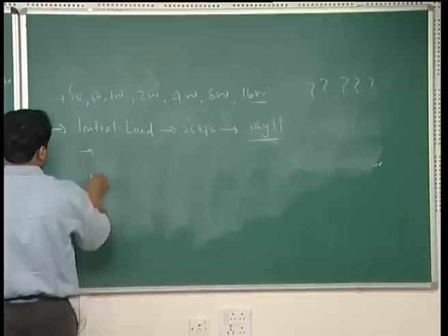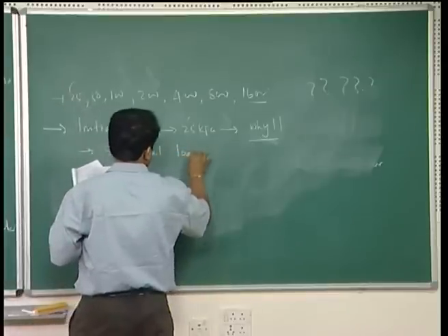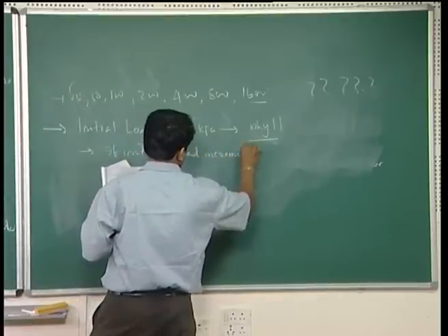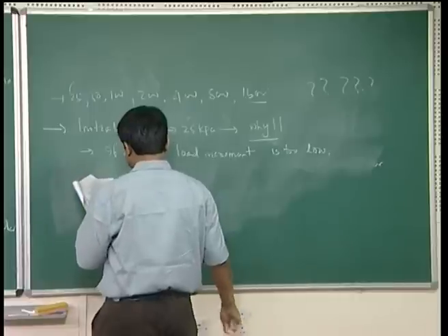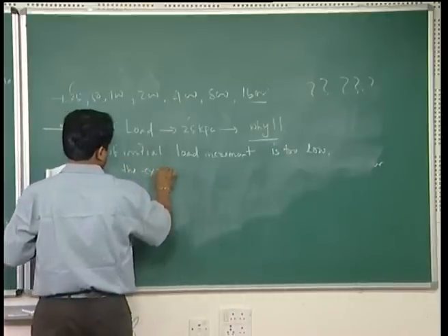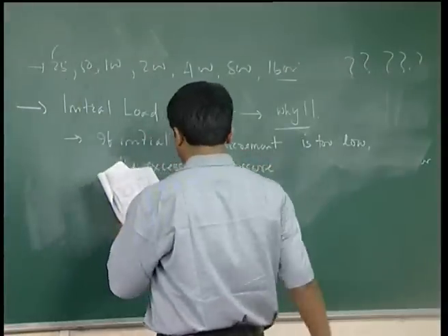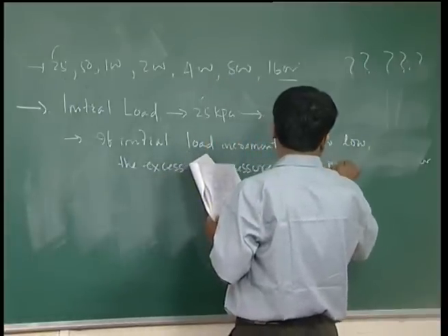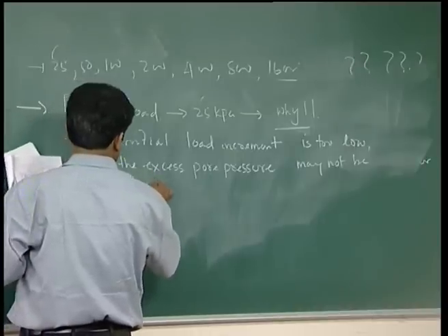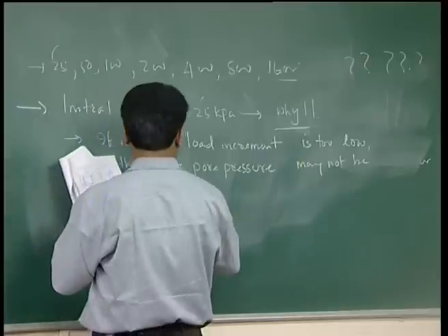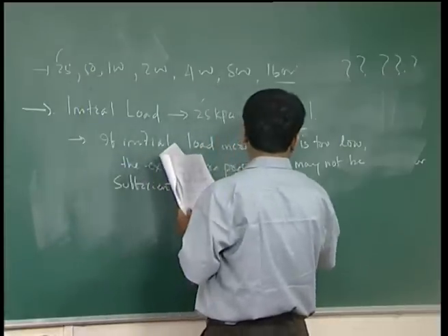The reason is, if the initial load increment is too low, then the excess pore pressure may not be sufficient to initiate pore water flow.